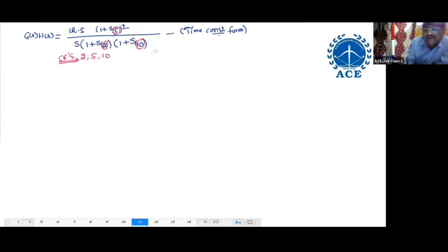On a semi-log sheet, the principle is the lowest corner frequency divided by 1 decade, meaning 10 times. That would be 0.2, but it should not be 0.2; it should be 0.1. The starting value should consist of only the digit 1. So start with 0.1. In case the starting frequency is 8, then where will you start? 8 by 10.